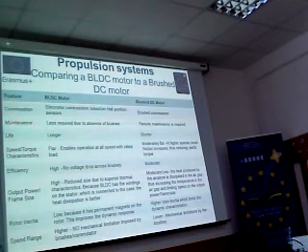And for maintenance, BLDC is less required due to the absence of brushes. The brushes will be touched to the commutator in order to get the energy coming out. So the brushes will be affected by time, so after some period of time we have to change the brushes.